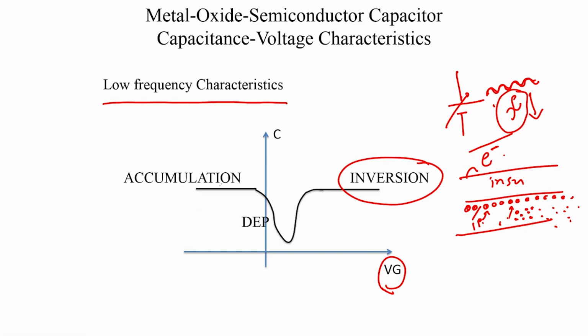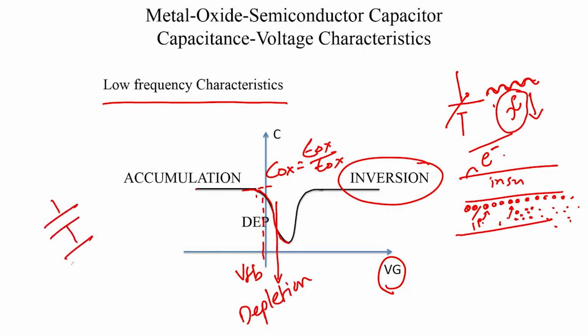And based on our discussion earlier, if you were to plot the capacitance versus the gate voltage, and sweep the gate voltage, let us mark our VFB somewhere, or easier to just mark Vg minus VFB. In accumulation mode, you have holes at the interface, the capacitance is equal to Cox, which is epsilon ox by Tox. But the moment the Vg starts going above VFB, the MOS capacitance starts entering the depletion mode of operation. So, this is all the depletion mode, and in depletion mode the Cox appears in series with the depletion capacitance, and therefore, the capacitance is now lower.